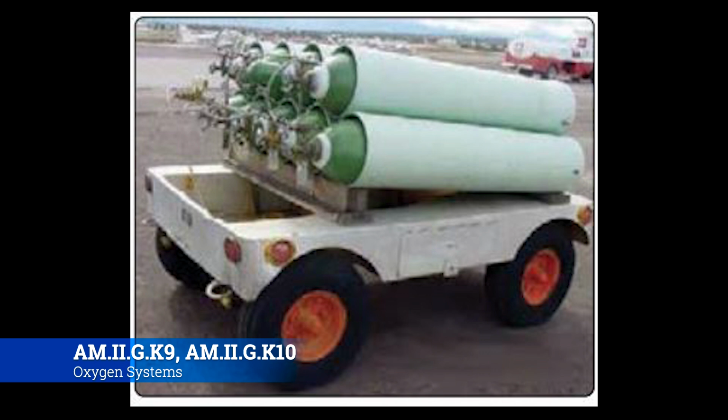Keep in mind that this oxygen will explode on you, so it's something you want to be very, very conscious of. You're going to make sure that you're super, super clean, because oxygen and hydrocarbons do not get along. They will explode. There are all these old stories of masks deploying, and some old lady put KY jelly or Carmex on her lips, and then all of a sudden she burns herself because there's a chemical reaction. So you don't want any sort of oil, any fuel, or anything like that on your hands or on your clothes whenever you're servicing oxygen, because it's a serious hazard that you need to be conscious of.